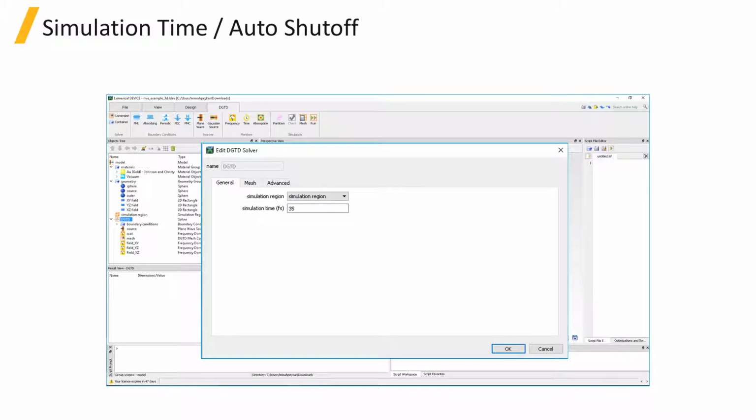This defines the maximum duration of the simulation to be performed and should be long enough so that the time domain light pulse has passed through the system before this time to ensure accurate simulation results. This ensures that the energy in the system has almost completely decayed before the end of the simulation. Ending the simulation too early will reduce the accuracy of your results, while running it too long simply means you have to wait longer to get results.